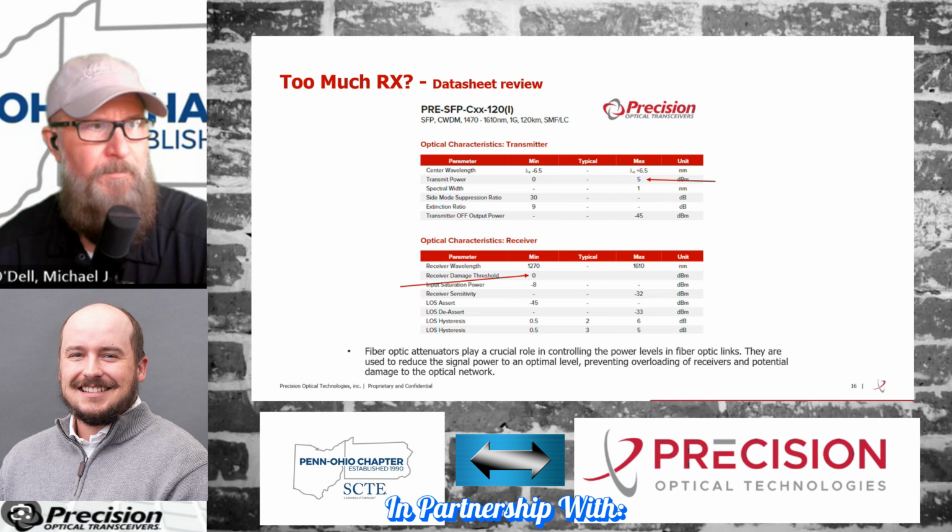So this goes back to why is there a 120 kilometer optic? Why wouldn't we use it in a 10 kilometer deployment? Well, unless you've got 13 dB of loss in that 10 kilometers, it's not going to link up. You're not going to be able to transmit and receive data. And this is just one example of why.